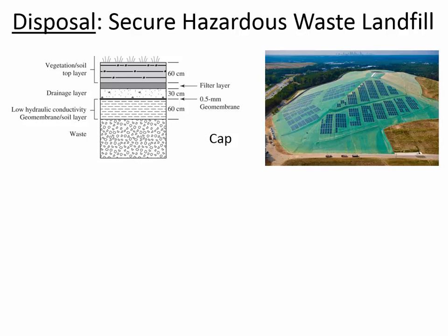Once the landfill has been capped, you can't build on top of it, so they've got some vegetation on it to help remove the water, through evaporation, and protect the cap. But another idea they had was to put some solar panels on the top. We can't put anything too heavy because it could threaten the integrity of the cap, but solar panels are light enough that that's one of the few useful things we can do with land that's been used for landfilling.